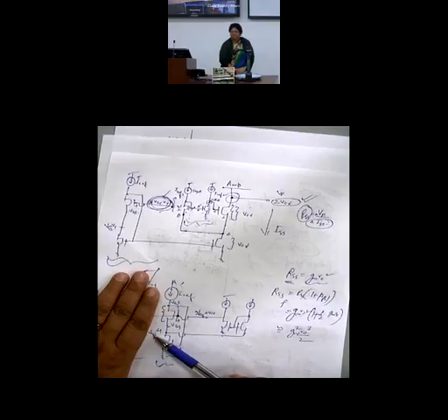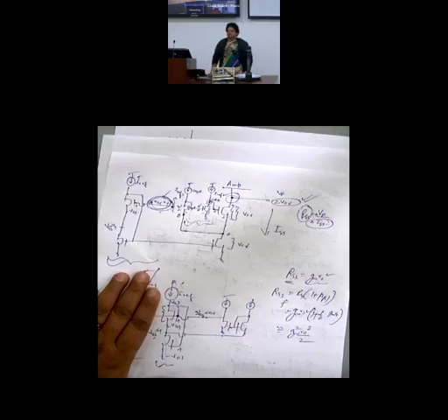It will be 1 V overdrive. Will it be in saturation? Yes. The minimum you require is 0.2 V overdrive. VT is 0.7. All transistors will operate in the saturation region.